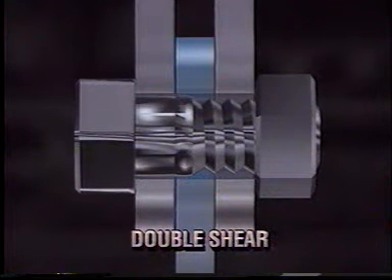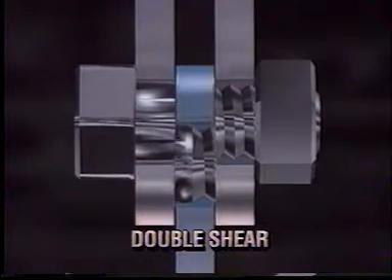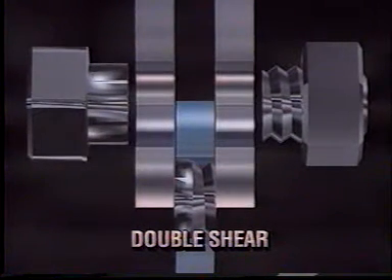Double shear involves three sliding or shearing members which cut a fourth member. The action is similar to that of a clevis joint under load across a pin, rivet, or bolt. The cross member is cut along two shear planes rather than just one plane as in a single shear.